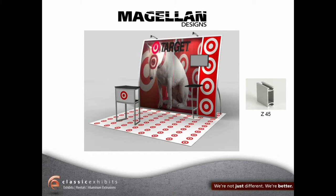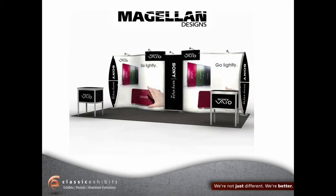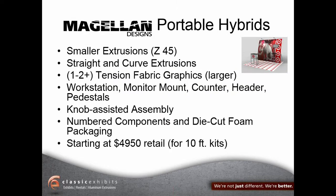So Magellan is almost entirely built with the Z45, and it's bent either on what you consider the larger flat edge, or we call the hard edge. You can see this is bent on the wider edge, and then things like the legs you see there and that leg are bent on the hard edge, so we do the bending in both directions. Z45 is a relatively inexpensive extrusion. So we're able to build these systems and do pretty elaborate things with the Magellan line and do the curves and still have very cost-competitive exhibits.